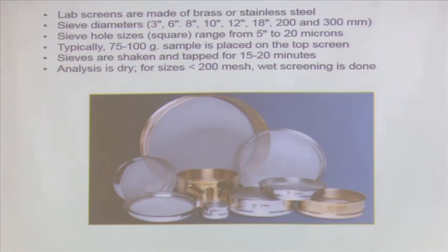That means you have got very fine strings like this, which could also be a screen surface, basically with regular square holes, and each hole is of equal dimensions. But in between, there is some width required, that is the wire thickness. So, suppose I have got woven wires put together, I must give some space for the wire thickness. When I say, suppose, 40 mesh, in 1 linear inch I have got 40 equal apertures, but what will be the dimension of each aperture will depend on the thickness of my wire. That thickness of the wire varies from manufacturer to manufacturer.